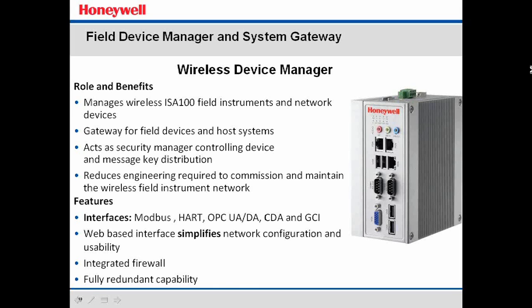The field device access point is a field device. It's an access point for field instruments only, meaning it's not a Wi-Fi radio. There is no real or perceived security issue here because there is no laptop chipset. There's no app for that. There's nothing that can associate or even see this network when it's up and going, for that matter. It's a low-powered frequency hopping mechanism, and a fixed channel wireless device like a laptop or a phone can't even see that it exists.